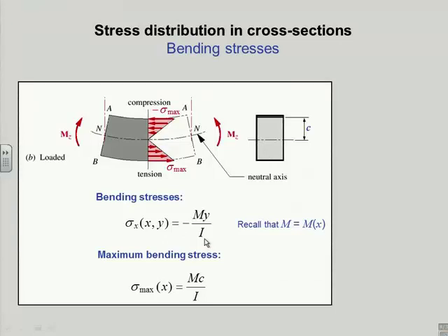And notice that h is cubed. So if you double the depth of a beam and leave the width the same, you get 8 times the resistance to bending. That's a very handy thing, because I can make the beam a little bit bigger and get a lot more strength, right, because of that third power relationship. The equations for these various cross-sections are in a table in an appendix in the book. And there's many more of them in other books out there.